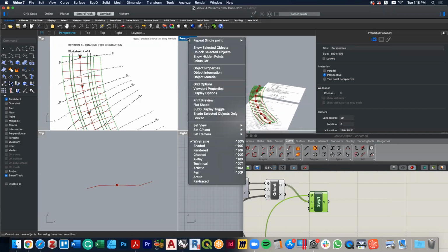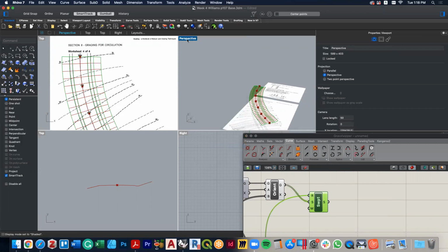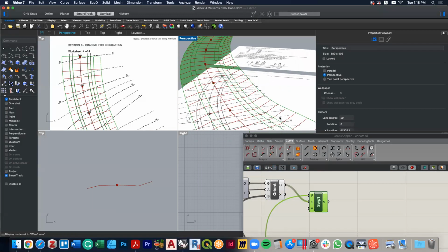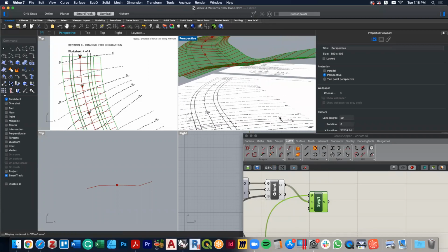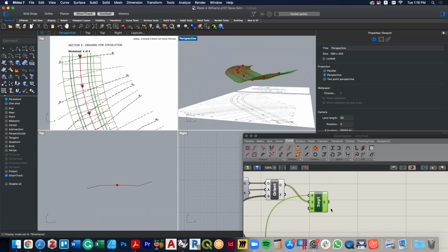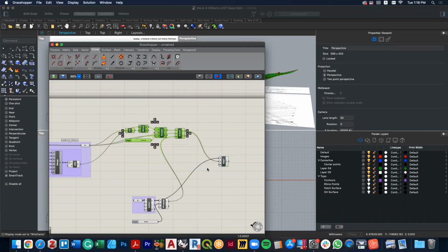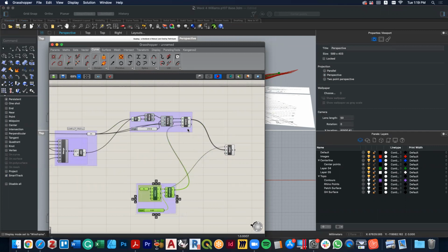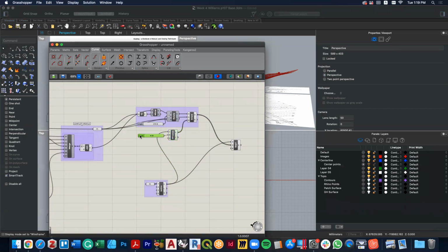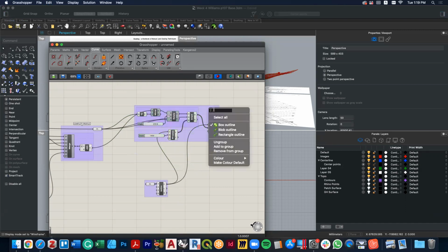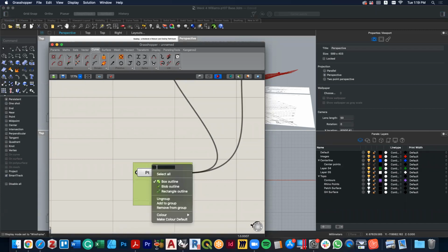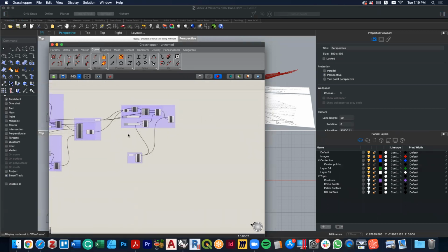Shading it doesn't make any difference because it's in Grasshopper, but you can see how that curve is there in the way that I've created. Now I've got those pieces of geometry, and I'm going to do some grouping again, because all of that was about setting up that situation. I group that as well. Really, logically, I could be putting that up there, because it's more about producing the curve, the sweep. So I'll group all of that together and call it sweep. I'll make sure we know that this is the rail. I've now got that there.